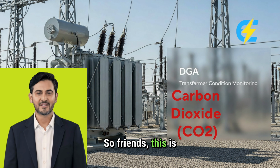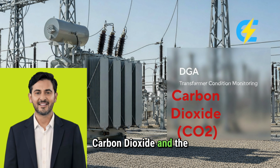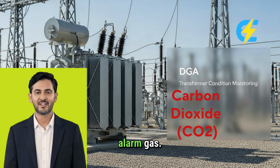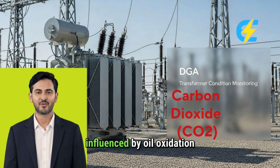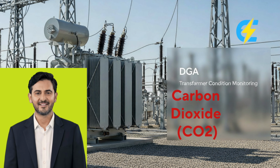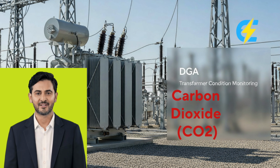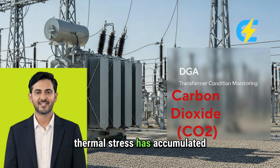So friends, this is the real meaning of carbon dioxide and the CO-CO2 ratio. CO2 is not an alarm gas. CO2 is a background aging gas. CO2 can also be influenced by oil oxidation and service age. Therefore, trend plus ratio must always be considered together. It tells you paper insulation has been aging over years. Thermal stress has accumulated slowly, and the transformer has a memory of its loading history.